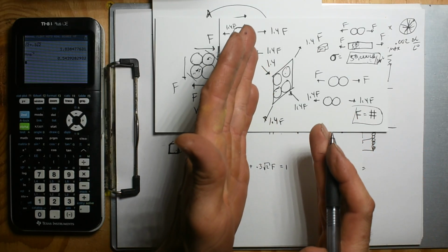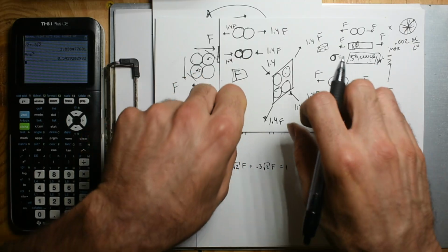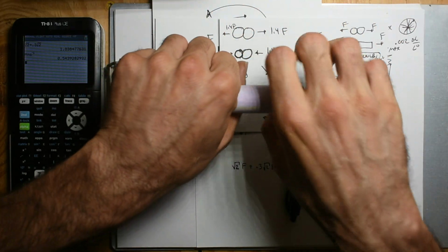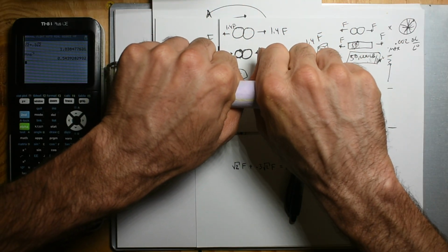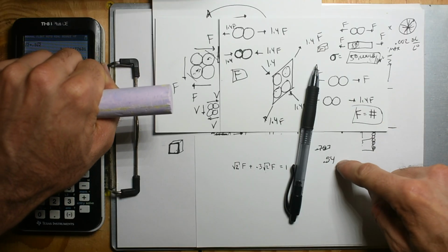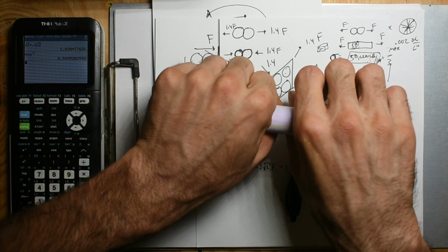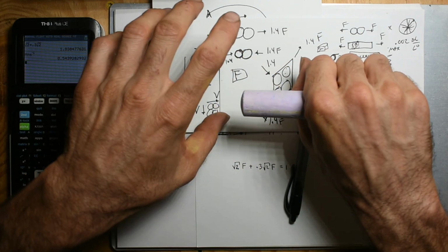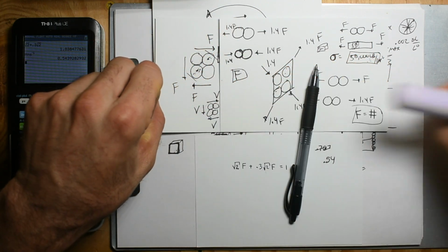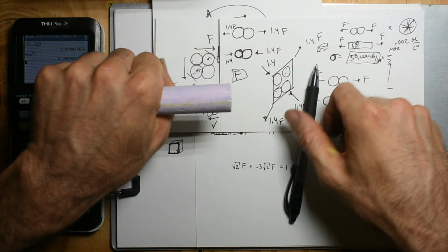54%. So if I'm shearing something, or if I have a bolt, if this is a steel bolt, and it requires 1,000 pounds to rip it apart, it's only going to require 540 pounds to shear it. So again, a bolt is going to take 1,000 pounds to pull this way, and 1,000 pounds the opposite way.